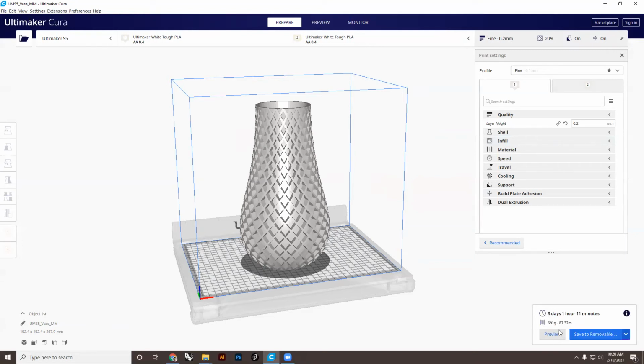So here we get just about half of that, where we're printing this in 3 days rather than in 6 days. So this is really something that you can use to control the speed of the print. If you're doing 3D prints as a test and you're really just trying to get a rough idea of the geometry that you're working with, always move that up and try to be in that 0.2 range. That way we can print the objects much quicker.